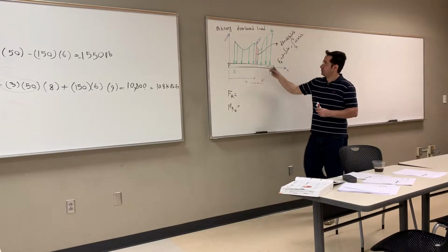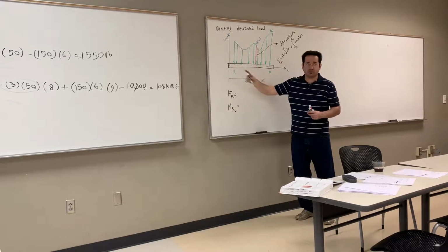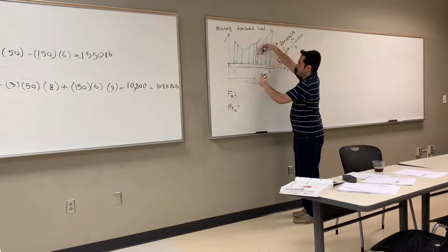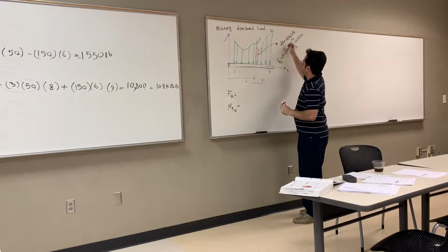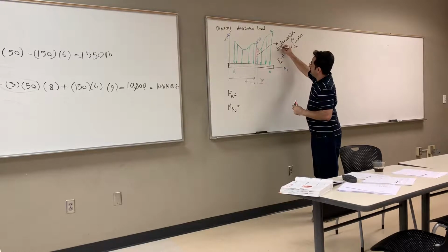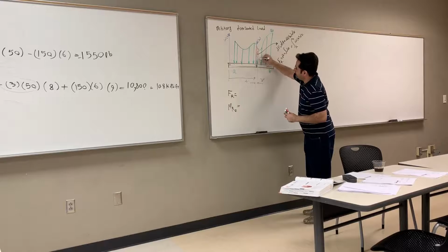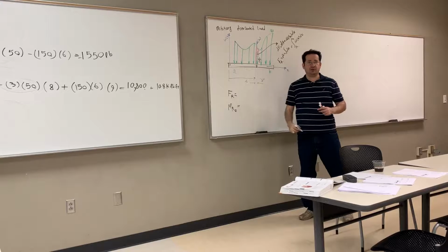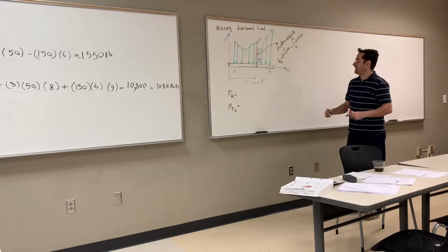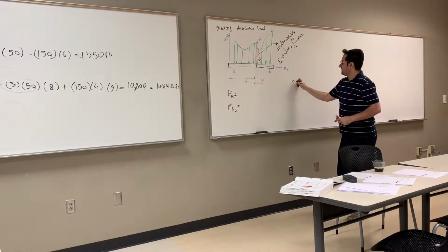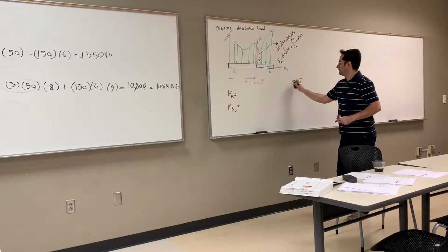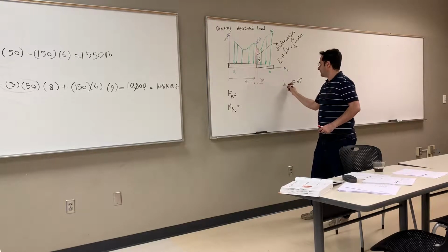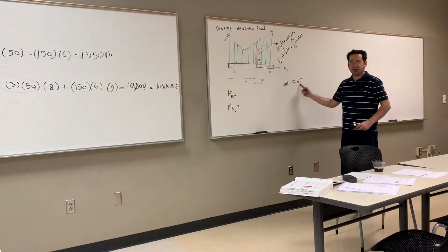What about moment? What moment does this little force generate with respect to 0, 0? Let's say this is df, right? So this dA is in fact also df. What moment does this tiny force generate with respect to 0? Yeah, times the distance. Yeah, x times df is equal to the moment it generates with respect to 0. So it is an infinitesimal moment.